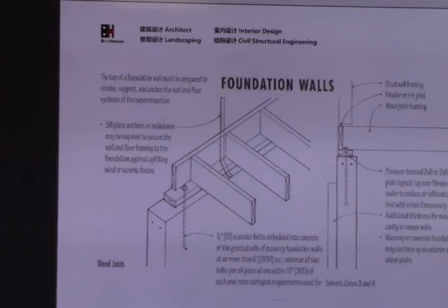A complicated shape has more corners, so at every corner we basically have a hold down. Hold down is for seismic. When the seismic load comes, the hold down is very important. There is a different result with and without hold down. Also, the hold down resists the lifting from wind. Gust wind can lift the building, so it's very important.